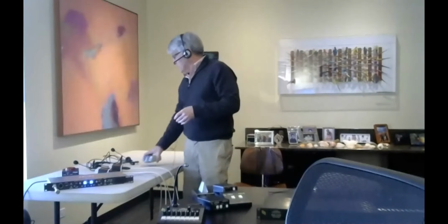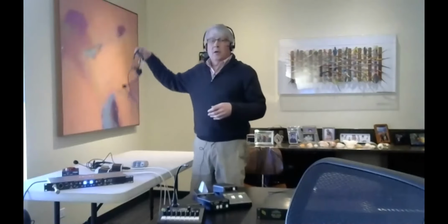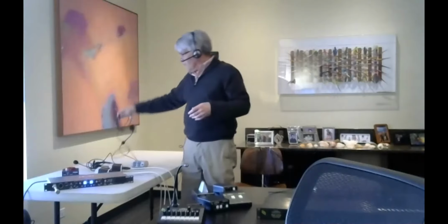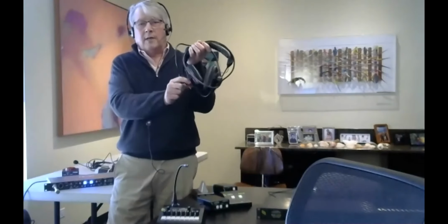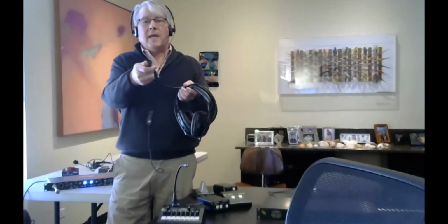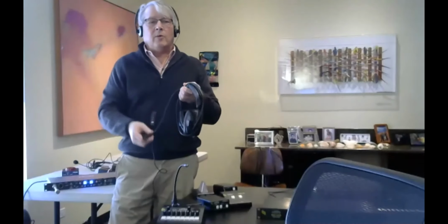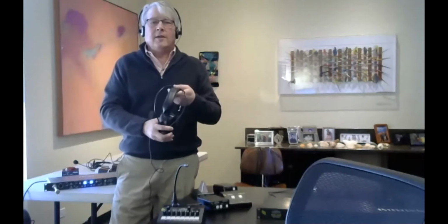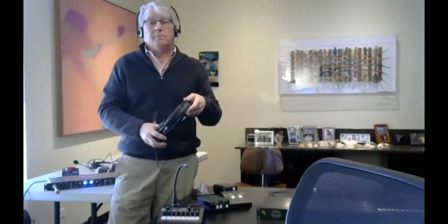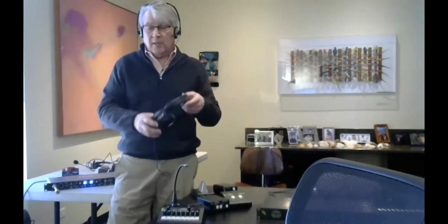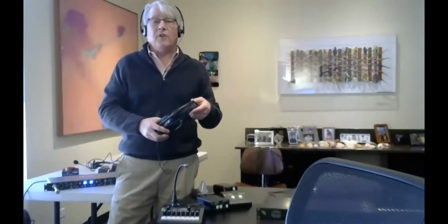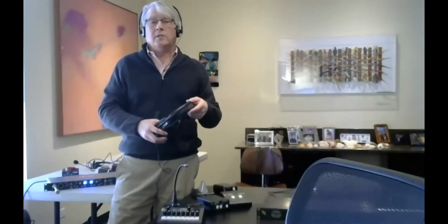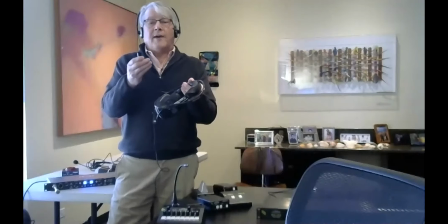And headsets, we've talked about a single ear with a 4-pin XLR. I also want to show you what's commonly used in the broadcast world, and that's the double ear, right? Left and right ear with a boom, and a male 5-pin XLR. So if you're out in the field and you're thinking, what am I seeing? There really aren't very many different headset choices. So you'll see it with single channel Clearcom. It's typically on the headset, a 4-pin XLR female. In the broadcast world, 2 channels, it's typically an XLR 5-pin male.